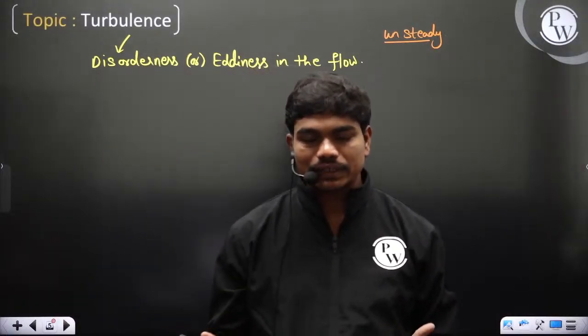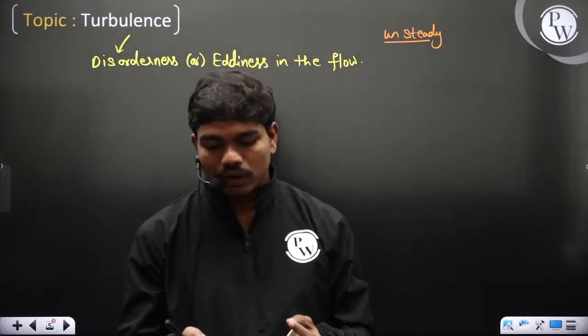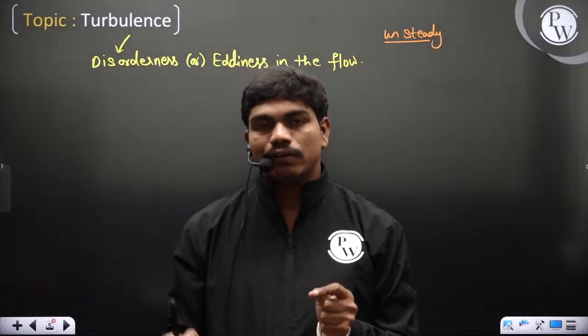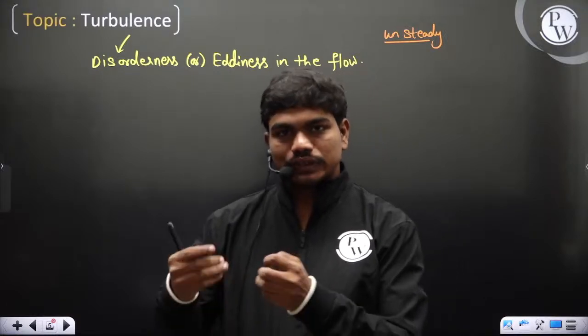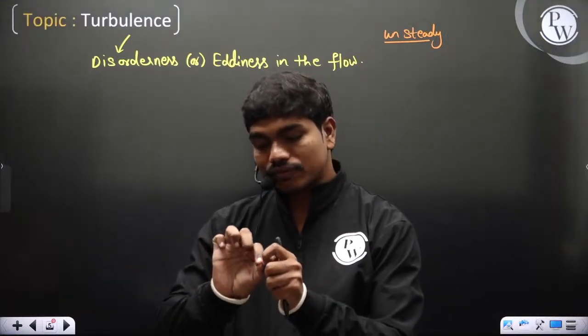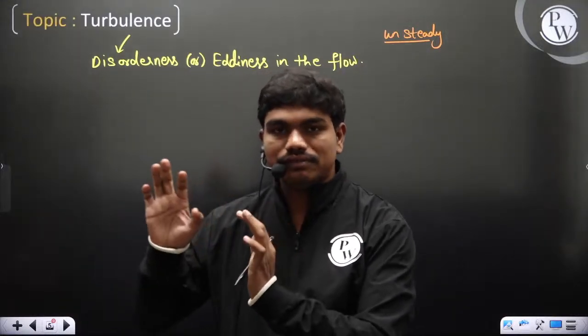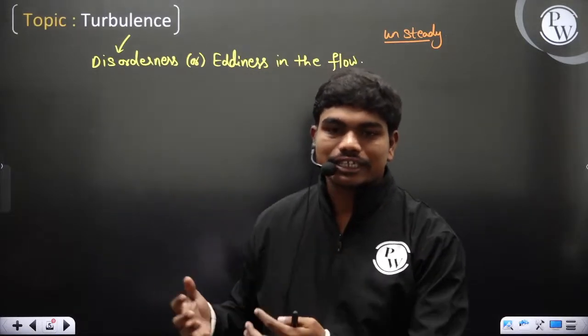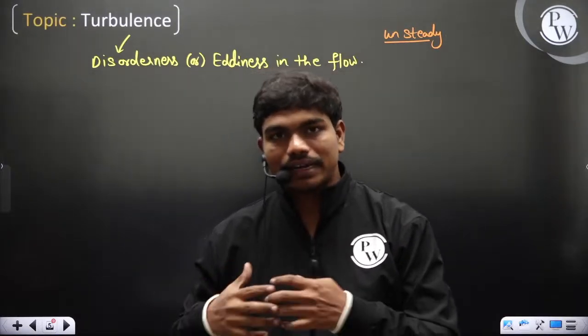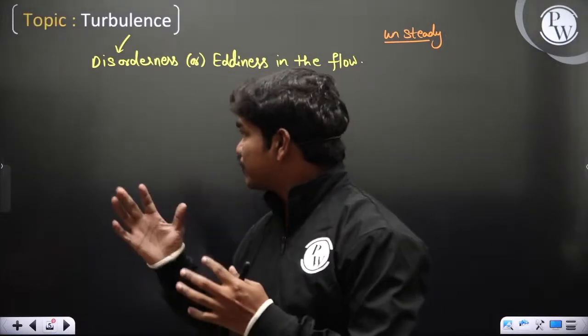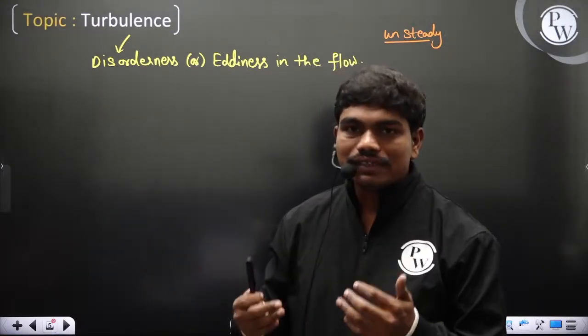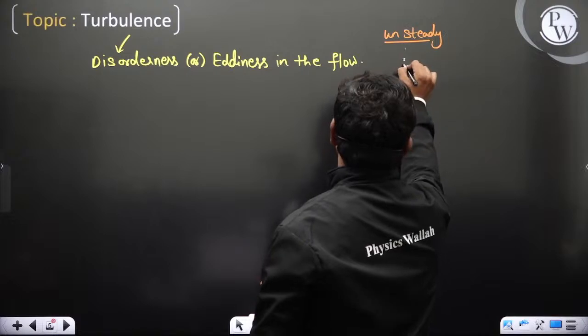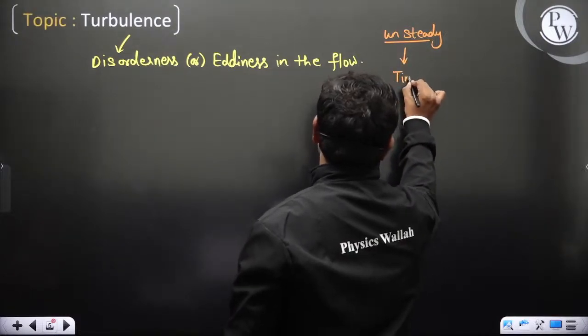For example, in the case of laminar flows, if a fluid particle is moving, once you make a steady assumption and keep things steady, the fluid particles continue to move in a particular fashion. But in turbulence, the particles keep on mixing and there is a lot of physics which continuously changes. So because of this unsteadiness, we take time averaged values.